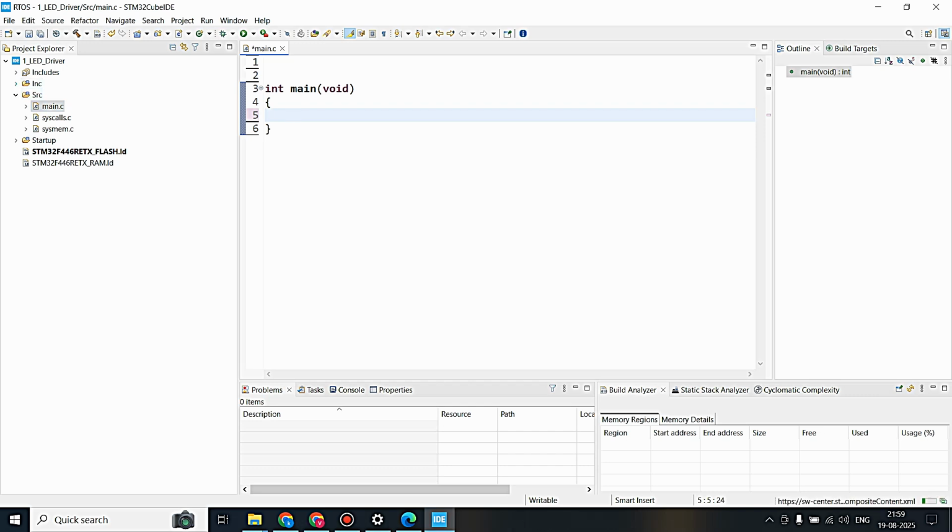And now getting into the programming part, we want the header file required for writing down the program. That is the header file which contains all the register structures of the microcontroller, so that we can access and write to the respective registers of the microcontroller with the help of the memory location of the microcontroller. So that is nothing but the CMSIS file required for our project. That should be provided by the silicon vendor itself. In our case, we are using STM32F4 series microcontroller. So the silicon vendor is nothing but the ST Microelectronics. If you are using a different brand, the vendor must provide that CMSIS file.